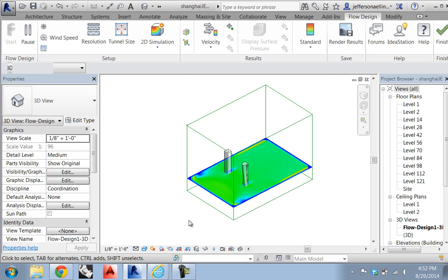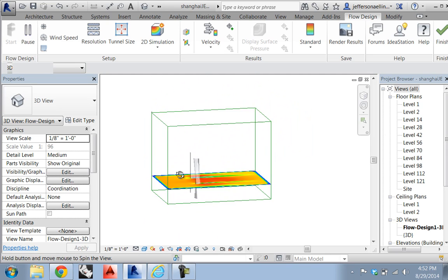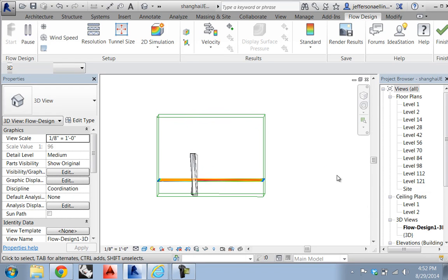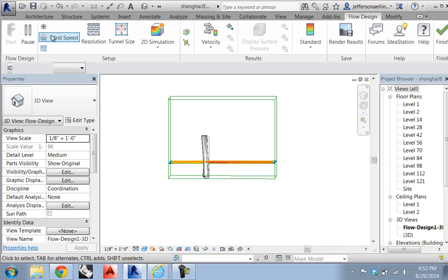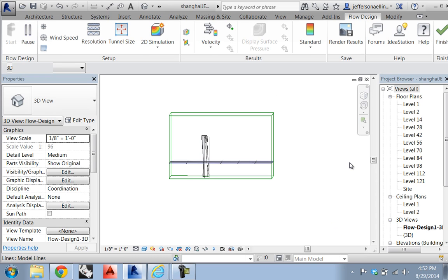And then you can do the same thing on the top and bottom as well. So right now our top is way higher than we need, so we can slide that down probably to about here. But again, we need a bit, oops, did I just cancel it? Again, we have to have enough space that allows for those voxels to resolve to undifferentiated or disrupted airflow, right? So we're going to that point.